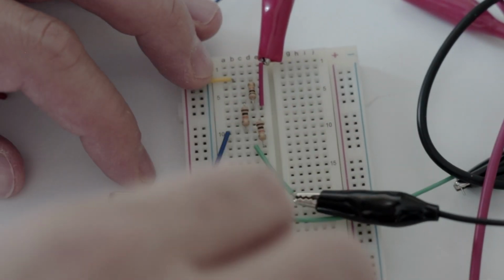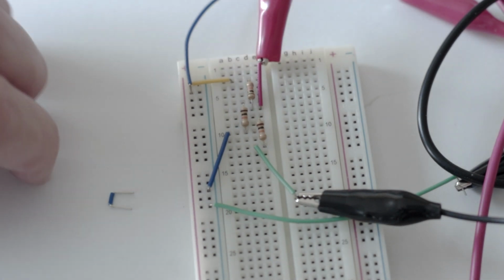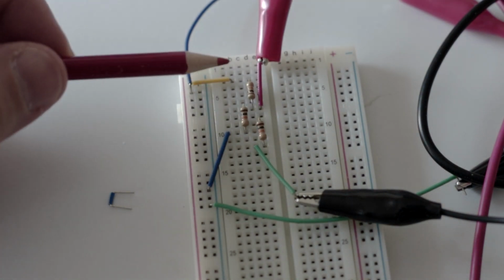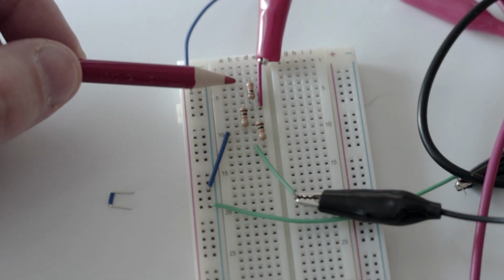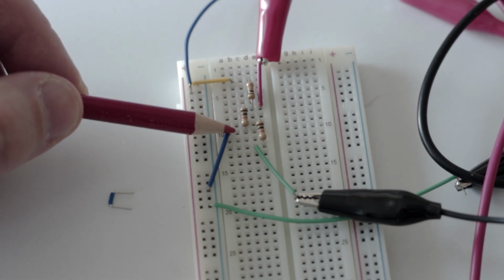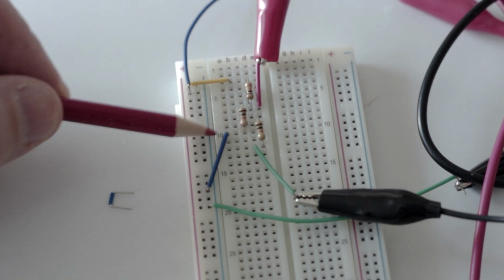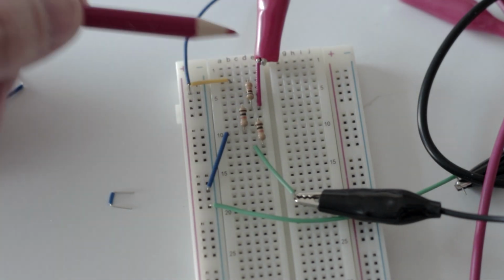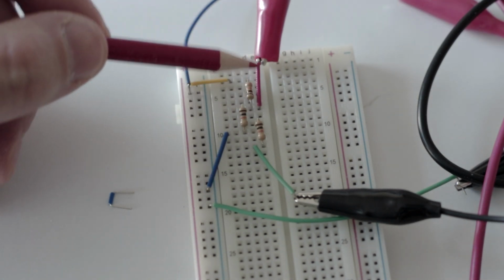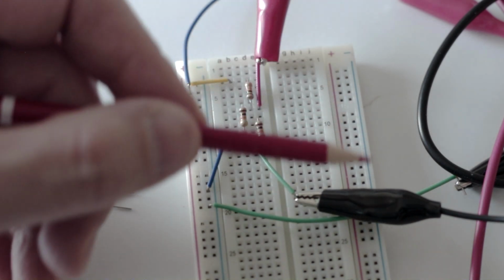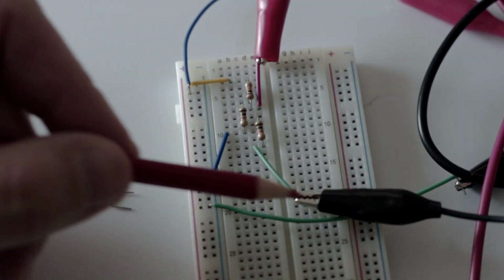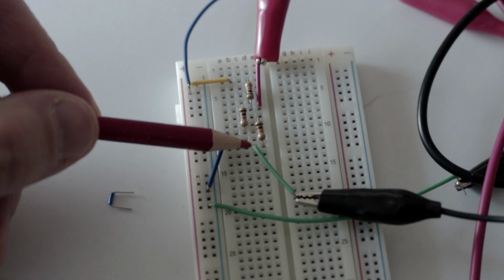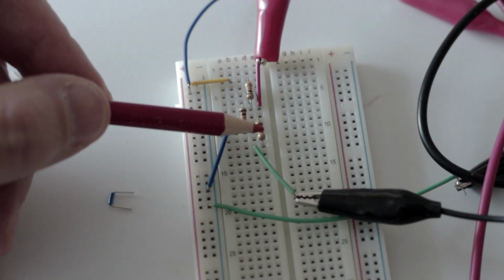Now R3 is actually placed upside down, kind of. Look, the current comes into R2, passes through R2 and goes to the ground. The other current comes after R1, goes to the multimeter through this red, gets measured, returns back through this black, and then R3.